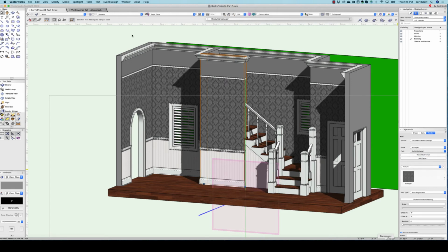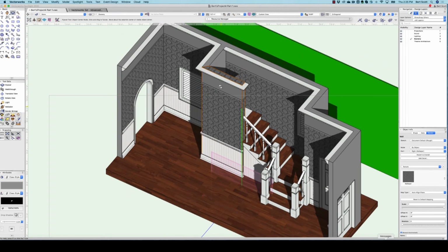You'll notice that I have control here over things like end caps and the top and the bottom. So for instance, there shouldn't actually be wallpaper on the top of the wall. Nobody's ever going to see that. So if I wanted to clean that up, I could, so let's see if we go to top, none.